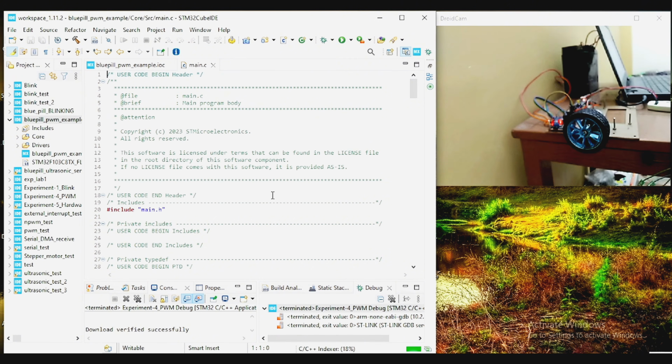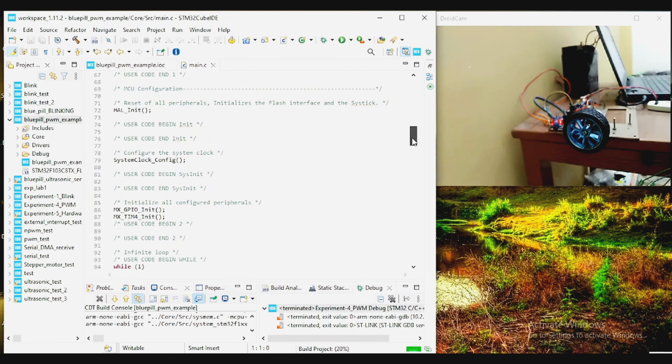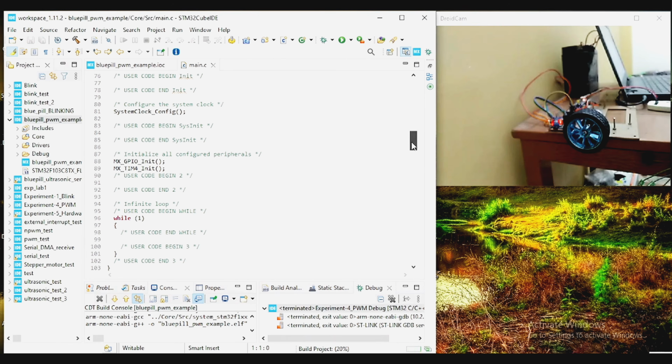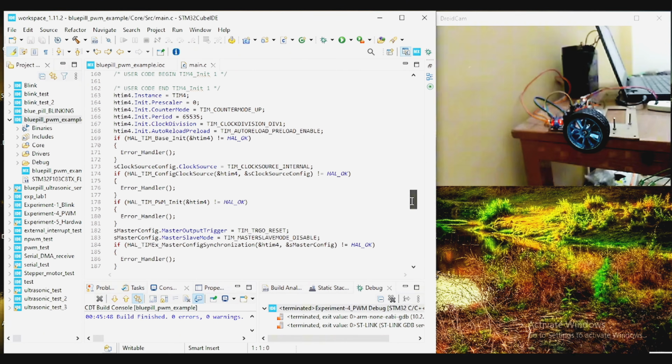Now we have a main.c file. With everything configured, we click Save and generate initialization code. STM32 CubeIDE now prepares all required HAL functions for us. Inside the main.c file, you will find the key function HAL_TIM_PWM_Start. This line initiates PWM output on the selected channels.